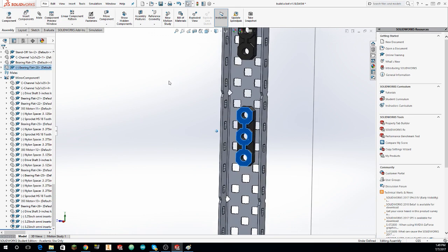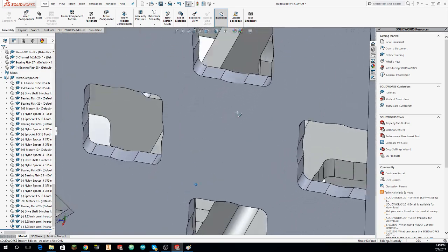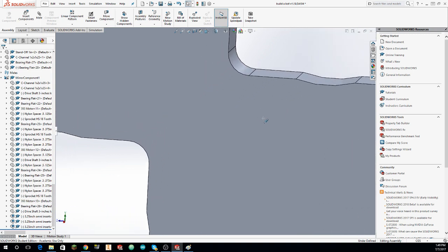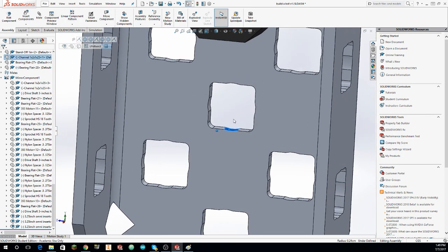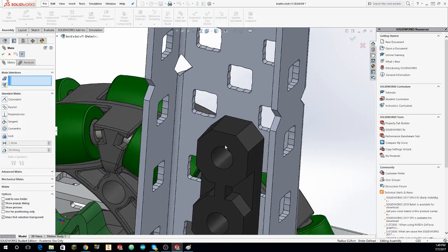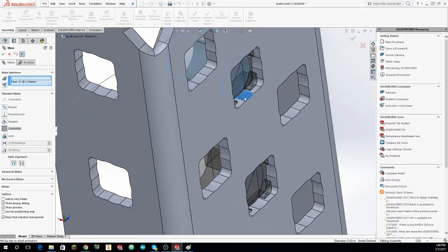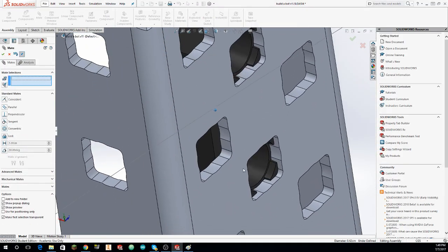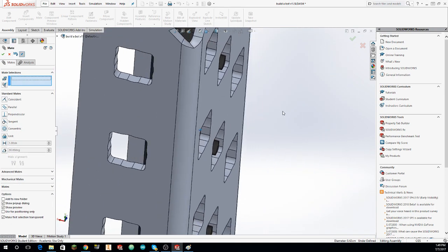You should take all your chances. They're actually circles through each hole. So what I did is that I took the normal faces and then I added a little curve here on all of them, so I can actually mate to that because it's a curved face, and that actually translates to the center here, which I'll actually do right now. So this guy here, so no, the inside here, like that. So it's really easy to constrain everything.